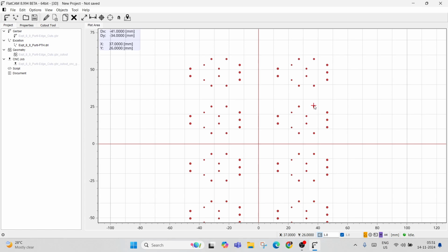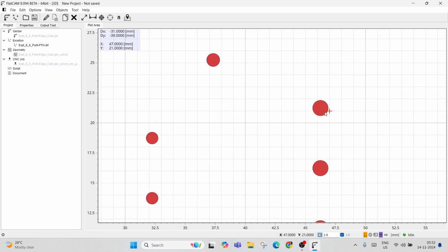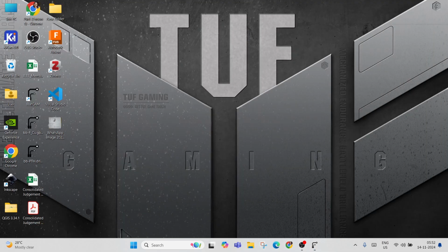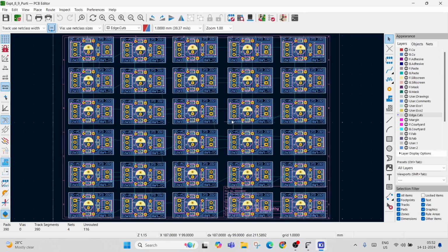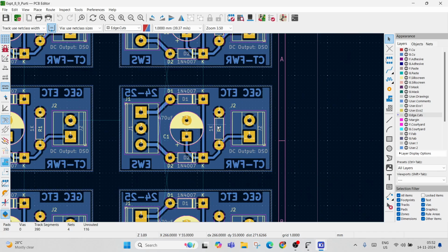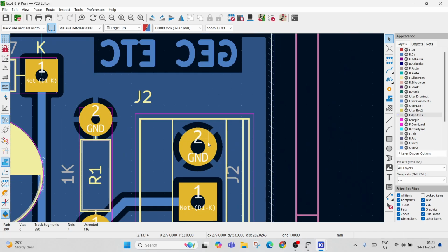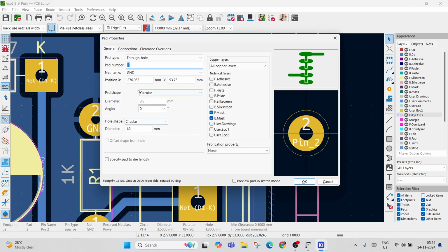we have managed to have pad size so large, 3 mm, taking in the largest size of the hole over here. To understand that, we will have to go to KiCad, and then we will understand what is the largest size. So the largest size is corresponding to these screw terminals. So you edit to see the properties.